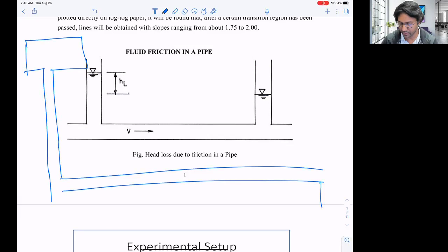You have to be able to calculate the minimum head, and make sure that the people who are going to use the water from your distribution system get that pressure, that head, when they open their tap. Then they can use the water from the supply system, otherwise they won't be able to utilize the water. So you have to make sure that you have the head there.